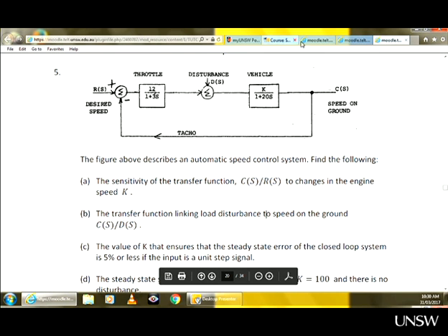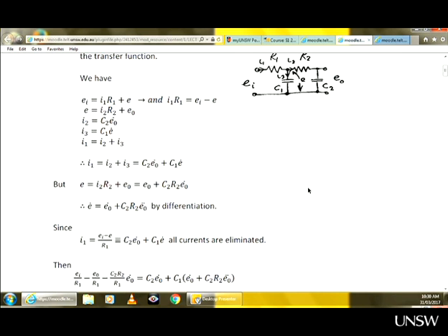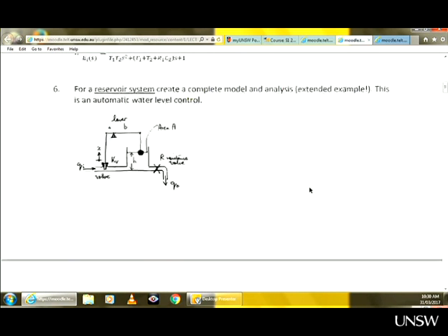Right, now, if you remember, this is now lecture 5, that we didn't cover this particular example 6, and we didn't at that time because this is an example of a control system. So this system controls height, controls the level of water in this tank. How is it done? Now you have a flow in, you have flow out, and obviously you have height. Now here you have a float. This float acts as a sensor. So as I said, electrical, but not always electrical.